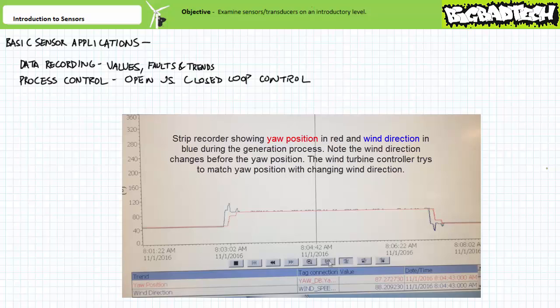On a continual basis, the control system records and stores this data relayed by the sensors. Additionally, this data can be transmitted to a remote supervisory control and data acquisition network. Should a fault occur, either an overcurrent event, excess vibration, or overspeed condition, the turbine control system can initiate a safe shutdown. Having access to all the data at the time of a shutdown, a technician, remote operator, or the automated system itself can make a decision to resume operation or initiate a call for service.